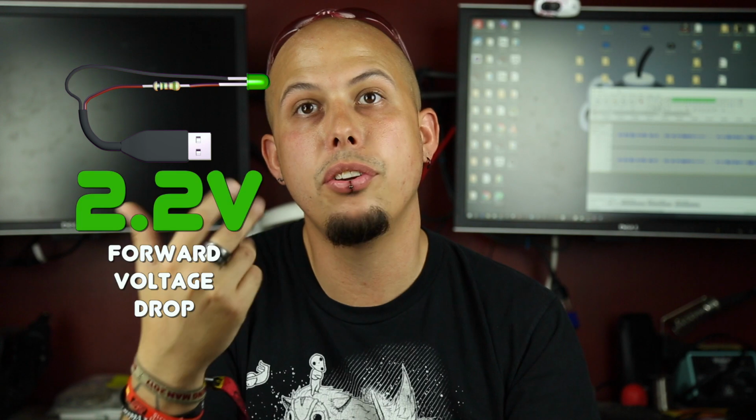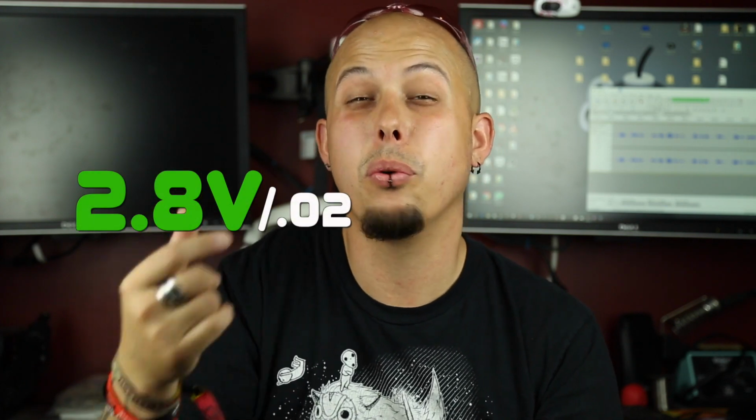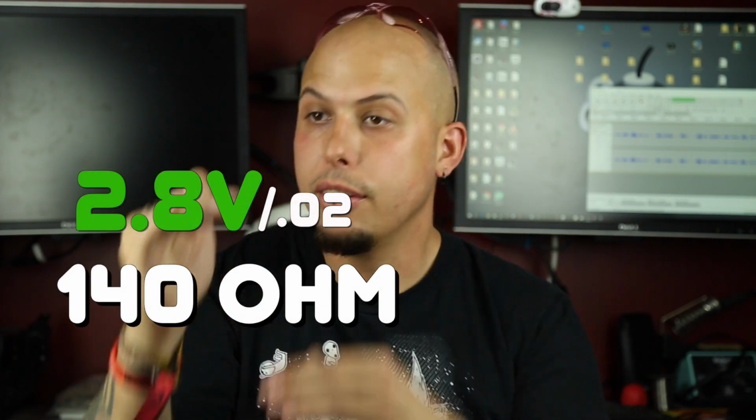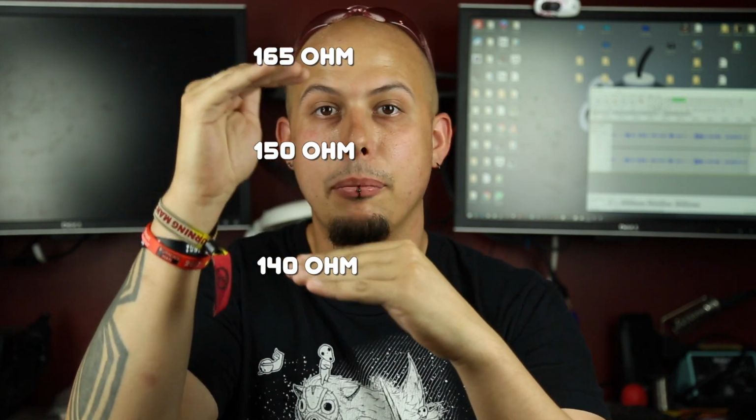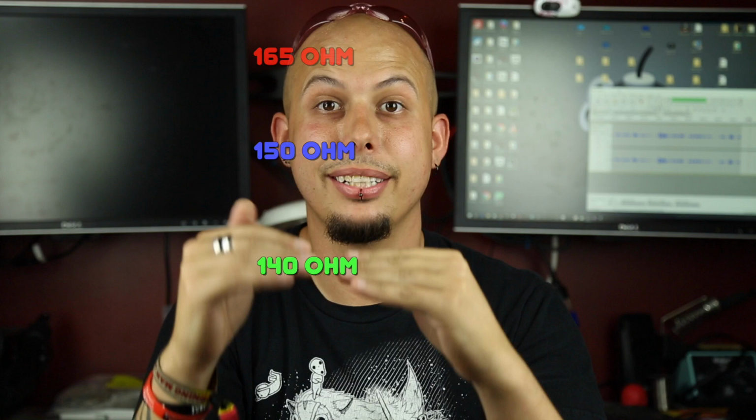And it's the same for the green as well. So the green was the 2.2 forward voltage. So it gives us 2.8 that we're working off of instead of 3.3 with the red or 3 for the blue. 2.8 with 20 milliamps will get us to the 140 ohm resistor. So that's our range right now. We have 140, 150, and 165 between red, blue, and green.